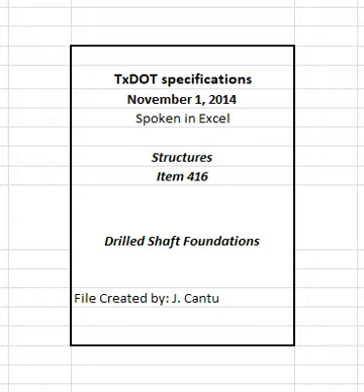Place the shaft to within the following tolerances. Vertical plumbness: 1 inch per 10 feet of depth. Center of shaft located under column: 1 inch of horizontal plan position. Center of shaft located under footing: 3 inches of horizontal plan position.